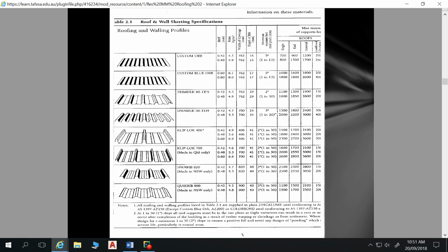However, when you've got a product like this, where your fixings go through your sheet and you'll see them, then you really want to ensure that all your purlins are in a dead straight line and that they're evenly spaced throughout the roof. It makes it look much nicer because you see the fixings on the sheeting.